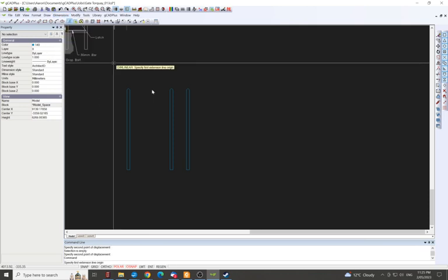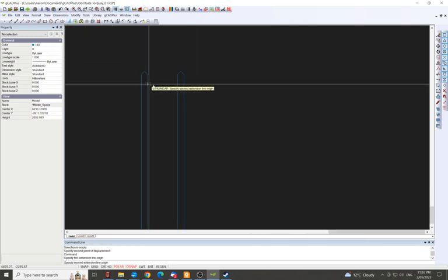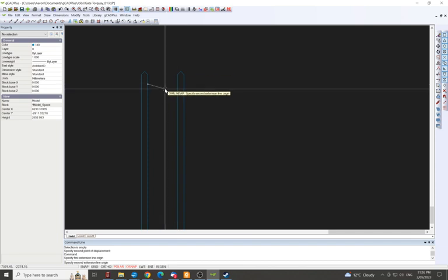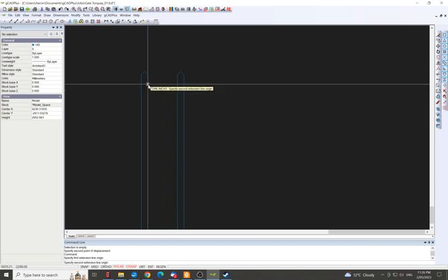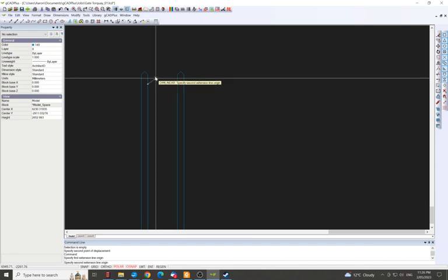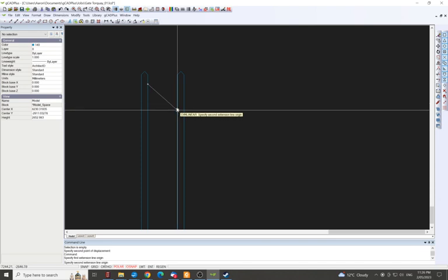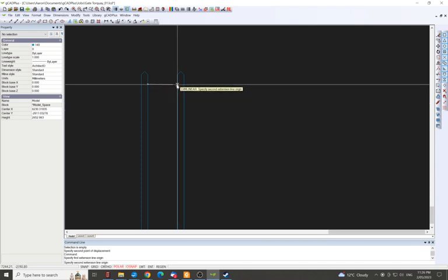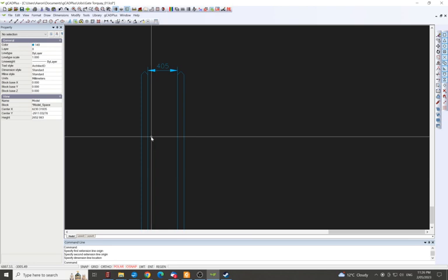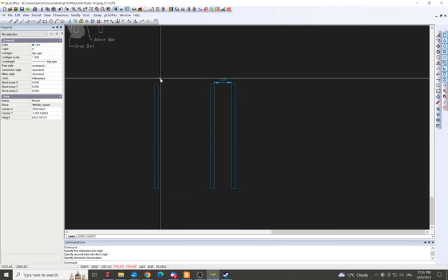This time we'll just use the dimension tool to check the opening. And again, the dimension tool does the same thing. So it snaps on the line there at 0. It polar tracks, but once you get onto this bit, it no longer polar tracks because it just slides along the actual line. But we'll just get it close enough to make sure it's overlapped, and we've got 405 there. So that's pretty good.